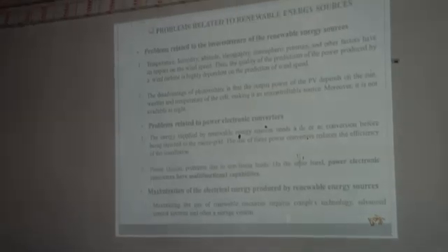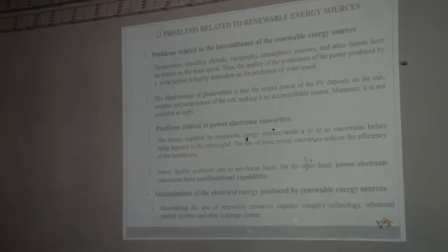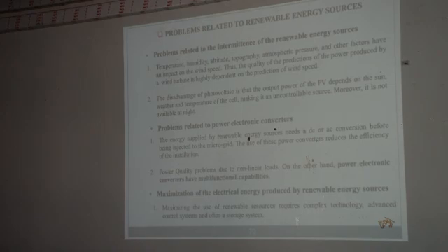Now we come to the standalone operation. When we come to the standalone operation, in the very beginning we have seen that there are some problems when we are working in the standalone case, right? What are the problems? Because now you have to stabilize your local grid. Sometimes you have high power generation and less demand, sometimes you have more demand and high power generation. So operating the standalone plants with renewable energy without energy storage system is practically not possible.